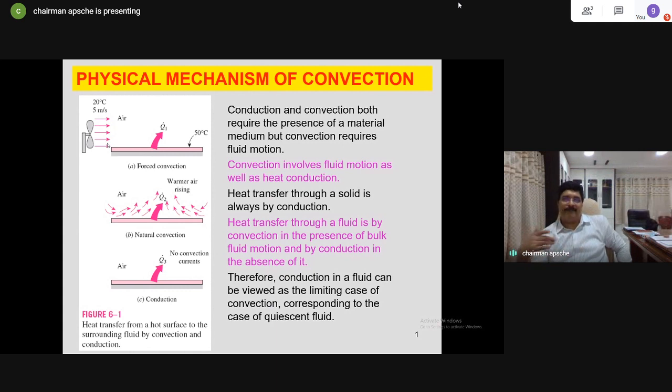All through the day, because temperatures are soaring, the heated molecules, being lighter, go and settle near the roof. The roof also receives radiation directly from the sun, and therefore it is a high temperature zone. The floor is not directly exposed to the radiation, so the floor is at a relatively lower temperature. So colder molecules naturally settle down, and heated molecules go up.